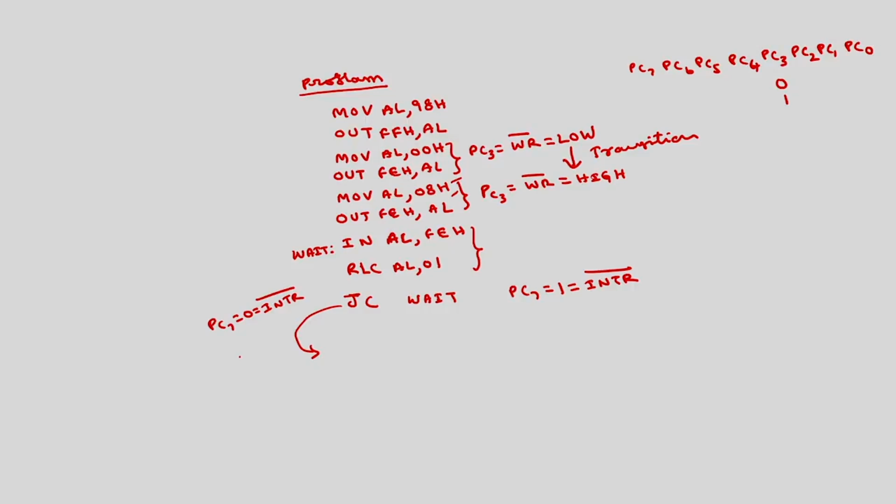Now, where is the data available? In port A. So, you have to read that port A. In AL comma, port A address is FCH. I want to store this data into BL register. So, you can move contents of AL onto BL. You can stop with HLT if you want to read only once. If you want to read continuously, instead of HLT you can write jump to UP. This UP is the label again here. So, in this way you can read the digital equivalent of the analog signal using ADC.